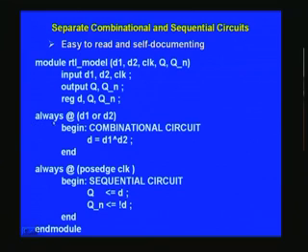Whatever is an output defined in a particular always block, you declare as a reg, as a general rule. Here it was an intermediate output, this d, which is nothing but the exclusive OR of 2 inputs, and so you declare this d as a reg, and that is what we have done. And naturally q and q underscore n are reg, being the D flip flop outputs.